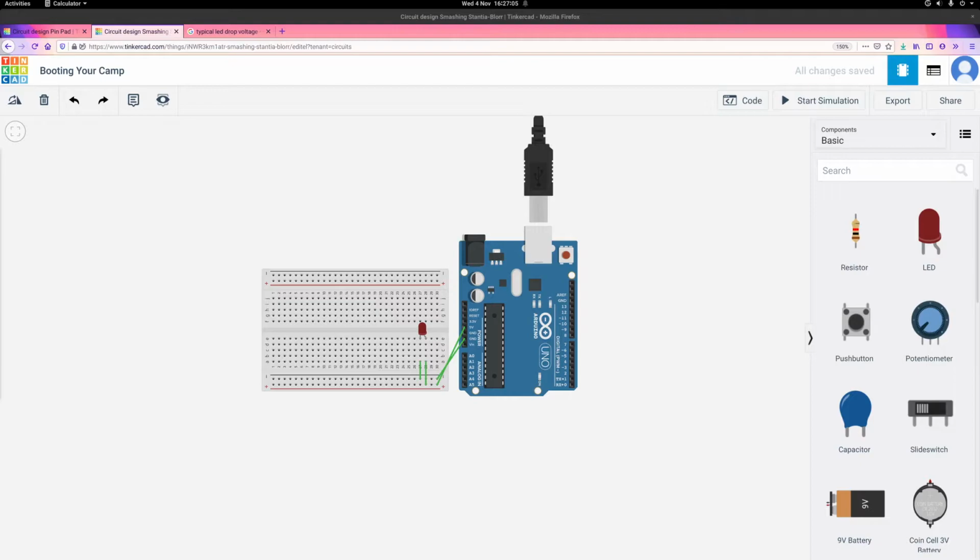Yes, okay, I got that as well. I concur that it is 165 ohms, and that would be enough to limit us to 20 milliamps. So I would agree with that calculation.